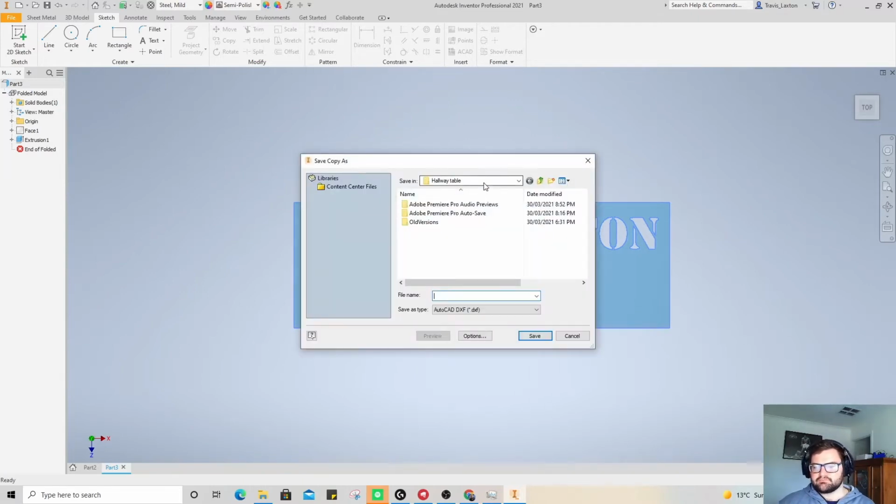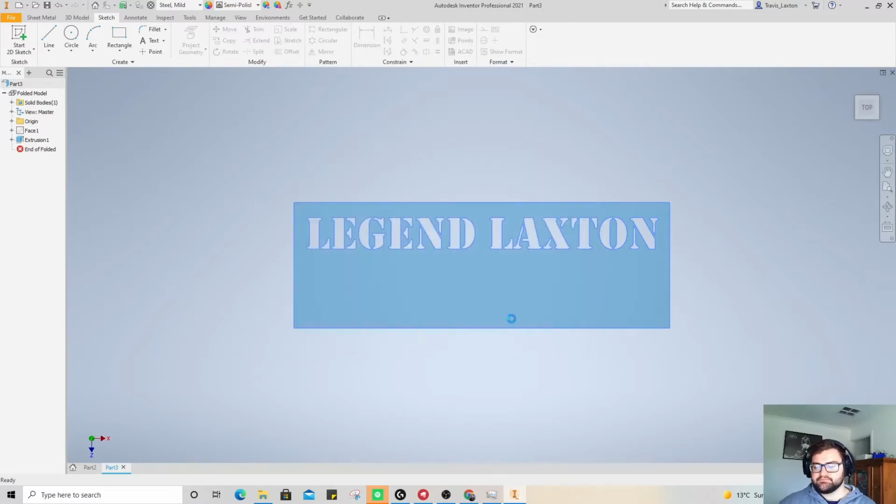as. We will save it in a projects folder just here. We always make a folder, and call it nameplate. Cool, and then just make sure we save it as a DXF. So try to make sure you always have a folder, make sure you name everything super simple so you know what it is. And we're going to save that.